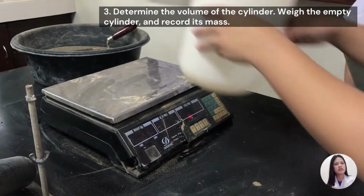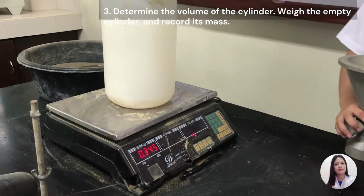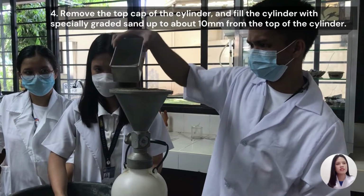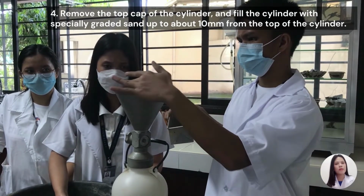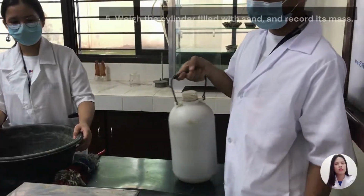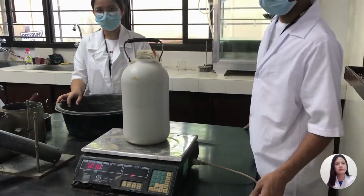Determine the volume of the cylinder and weigh the empty cylinder and record its mass. Remove the top cap of the cylinder and fill the cylinder with specially graded sand up to about 10 mm from the top of the cylinder. Weigh the cylinder filled with sand and record its mass.